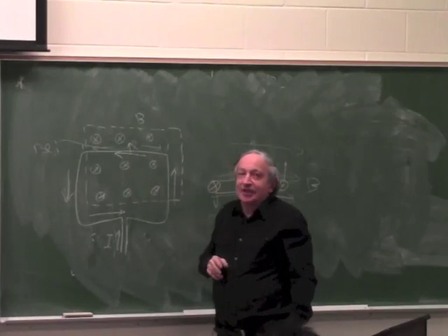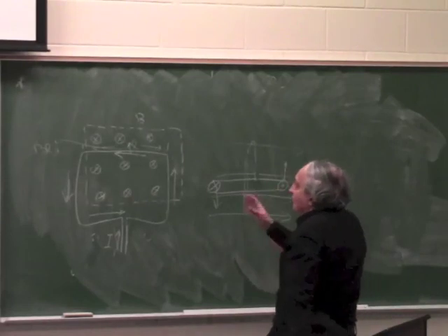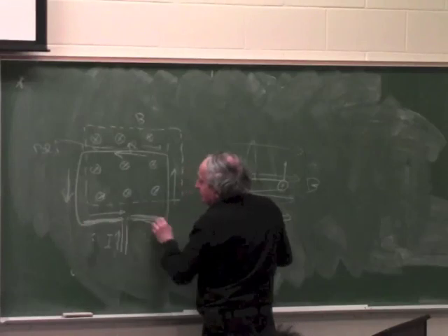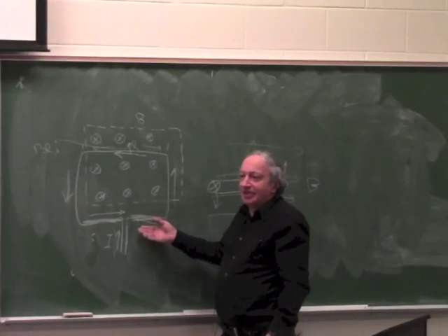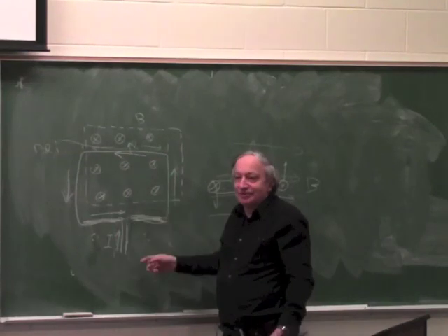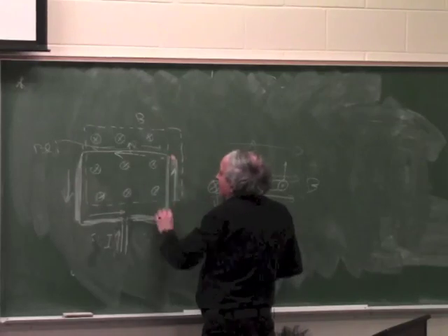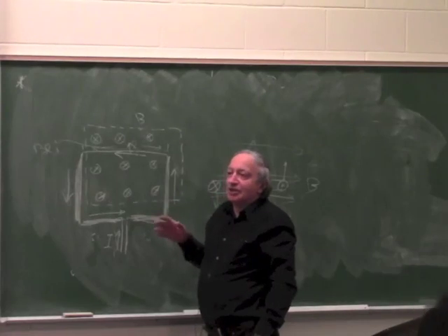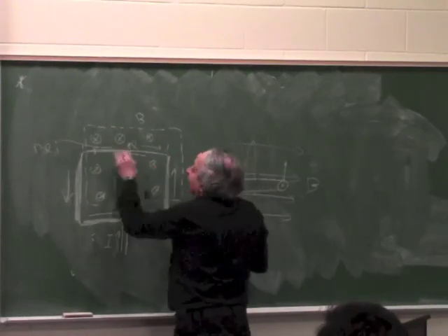And this shows you already the first problem with moving coil actuators, because if I look at a loop like this, this part has to be outside the field, otherwise the force will cancel out. So this part adds weight to the actuator but doesn't do any work. But I have to have it because I have to close the current path to a loop. Now these two parts add weight but create opposing forces which cancel out. So basically the only part of this whole loop which creates a force is this part.